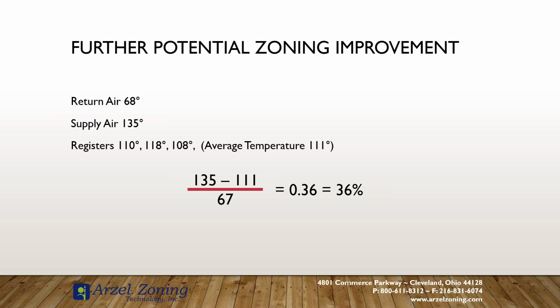Yeah, I've got them. But this is just a very simple thing. I'm taking my temperature rise. That takes what, 10 minutes? If I'm letting my equipment run for a period of time to stabilize, I get my temperature rise. I'm taking my return, my supply, and then I kind of walk through the house and I get the average of 3 to 5 registers. Once I have those 3 numbers, I can easily calculate out a BTU loss for their ductwork, and I can say there's room for improvement.